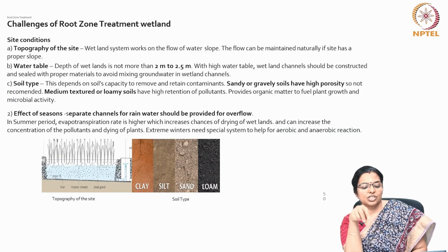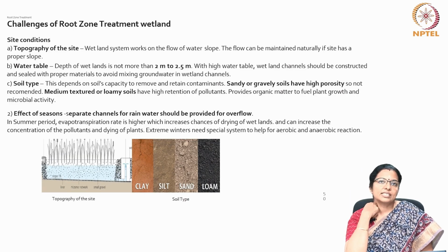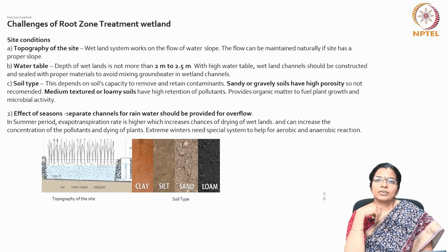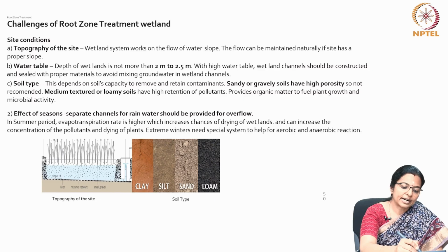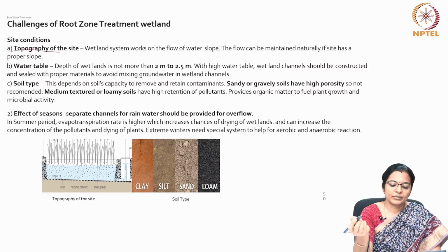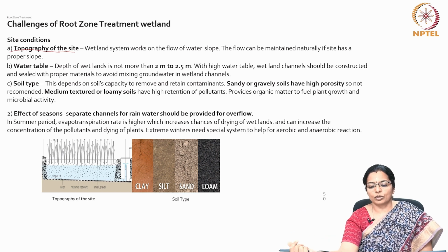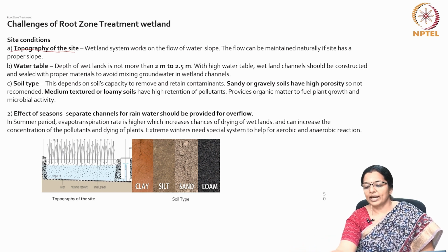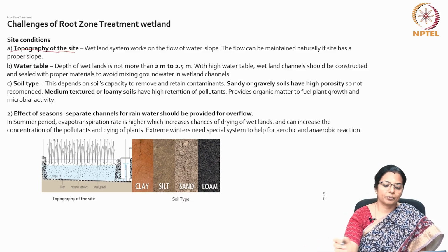Let us look at the challenges of root zone treatment wetland. First is the site condition. The topography of the site is an important criterion. So, wetland systems work on the flow of water by slope. The flow can be maintained naturally if the site has a proper slope.